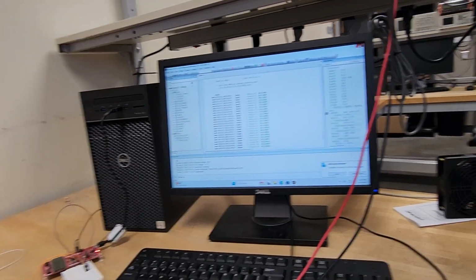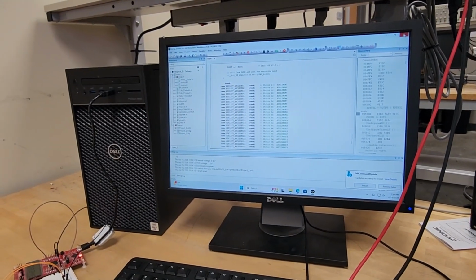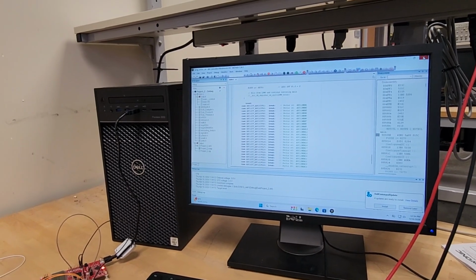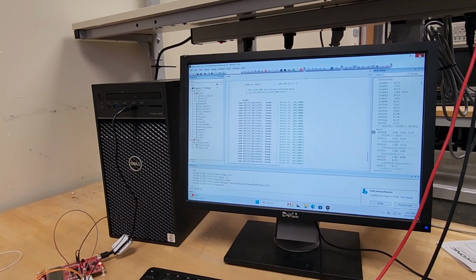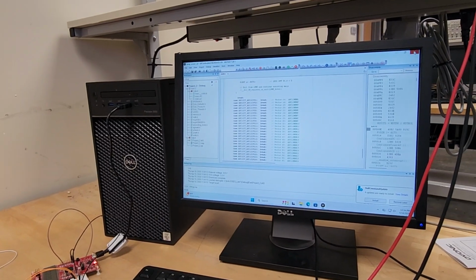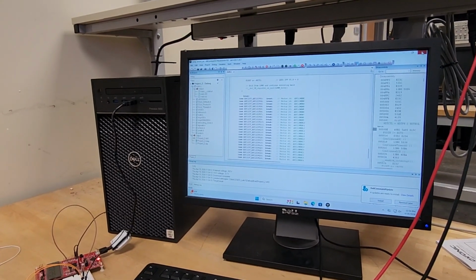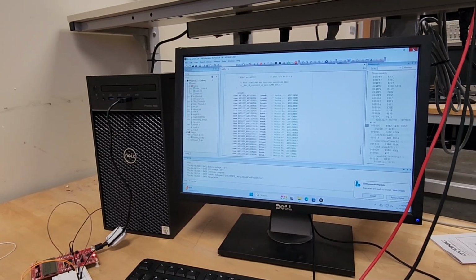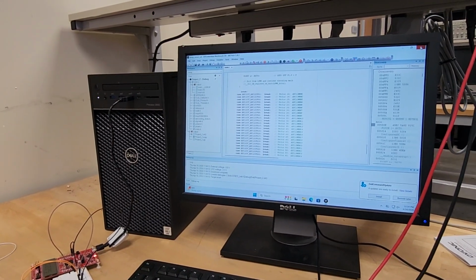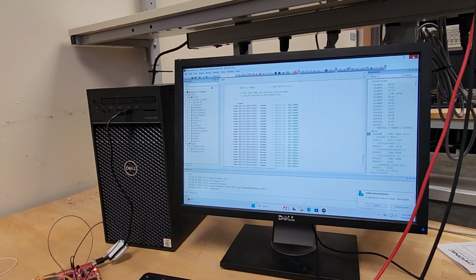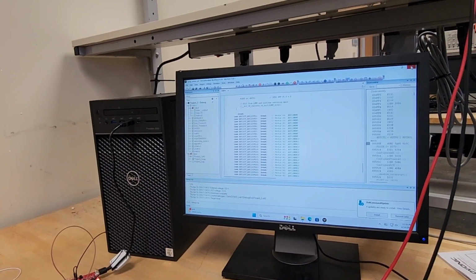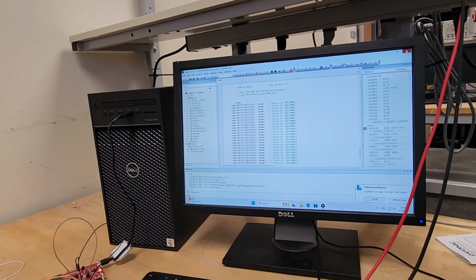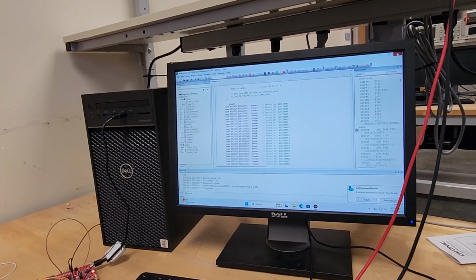The code itself is written in C and compiled using the IAR Embedded Workbench IDE for MSP430. The program configures the ADC to read channel A3, sets up timer A to trigger once per second, and initializes the LCD controller so the temperature can be displayed on the 6-digit segmented LCD screen. Every second the timer interrupt starts a new ADC conversion.